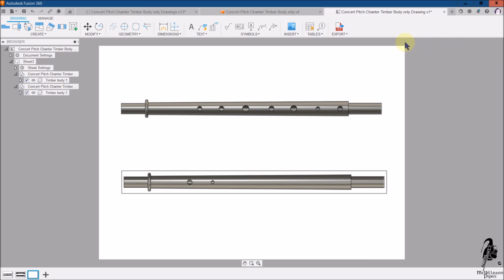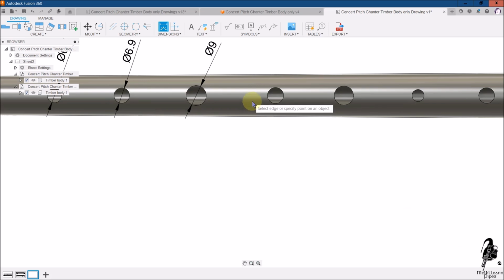Now we pick up dimensions. Hit escape. That line will go a bit away after a little while. So dimensions. Let's have a look. And it picks up the diameter. You can place these wherever you like. I'm going to go slow here. As you bring the cursor around the hole, you can select different elements of the actual hole, including the center.